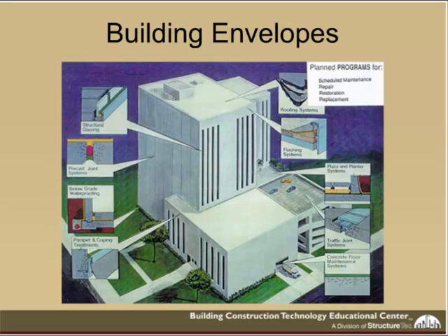First, what is a building envelope? A building envelope is all of the components that keep the exterior elements, specifically water and moisture, from entering the interior of the building. It really includes all of the components shown within this graphic. It includes your roofing system, your wall systems, and your window systems. It includes all of the flashings, copings, various components, joints, sealants, below-grade technologies, really anything that protects the interior of your building from the exterior environment.